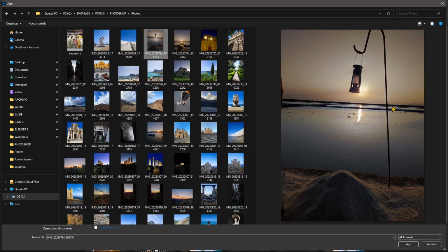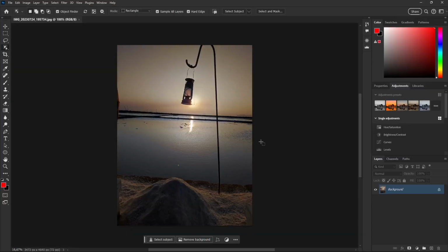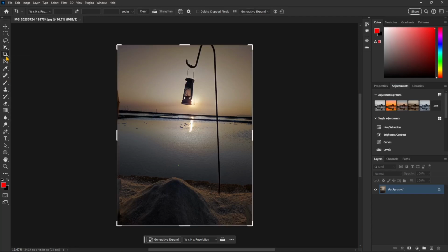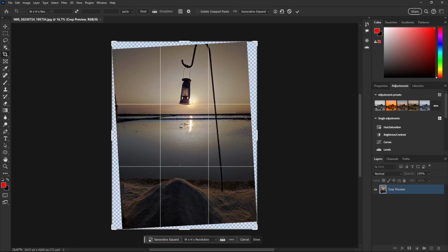So there is a tool in Photoshop that can help us. And actually we already use this because it's the cropping tool. So again, it's about cropping, but this time we're not gonna only crop, we're also going to adjust this image. Now you see up here, you have a straighten tool. Now all we need to do once this is activated is click with the left mouse, and then hold and drag this kind of a tape to define the position of the horizon.